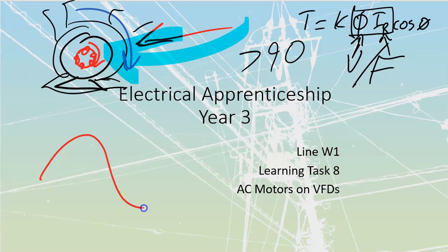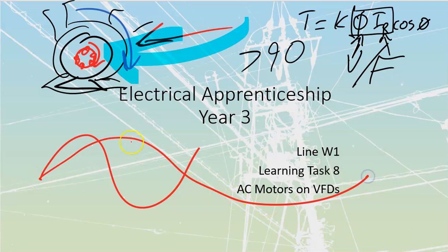If you take a look at a regular AC sine wave, that's going to be this thing at 60 hertz. If it's going to be at 30 hertz, now I'm going to have twice as long. And if I take a look at the length of time that I'm at a peak value of voltage, which means I'm going to be running a peak value of current through those motor windings, I see that this has increased. So if I'm going to be running at a super low frequency, I have to upsize my motor so that I don't cook off the windings, because I'm running a peak amount of voltage and peak amount of current for longer periods of time.